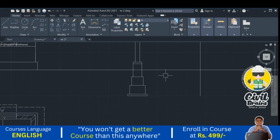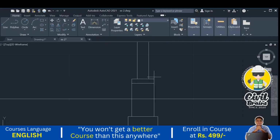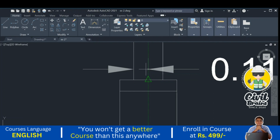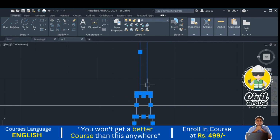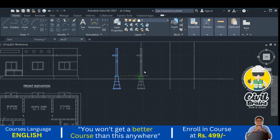How to copy this one? I just copy this from this center to this center. What is this wall center? This is our wall center, correct? I just check what our wall center is, 0.115. Okay, this is our wall center. I just select this, copy the wall center, and paste here: 1, 2, 3 and the 4. All the 4 walls will be there.